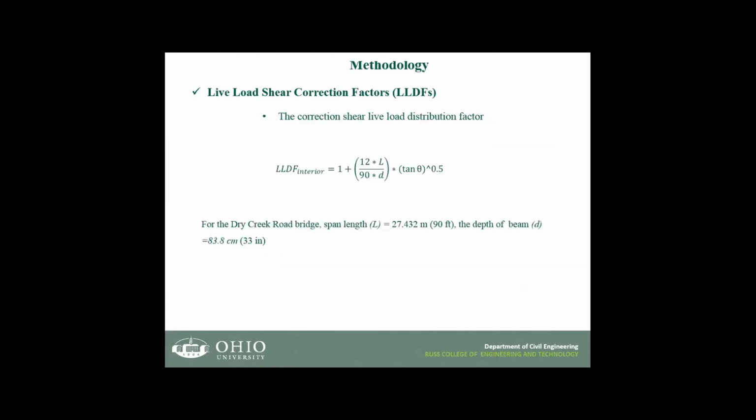This is the correction for the live load distribution factor shown in the LRFD 2017, which is related to the length of the bridge, the depth of the beam, and the skew angle.